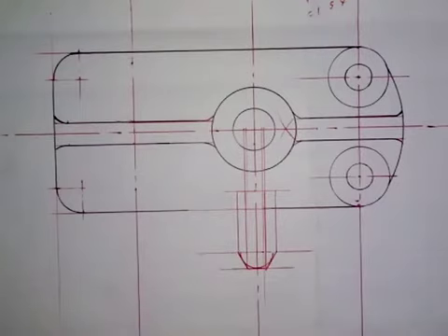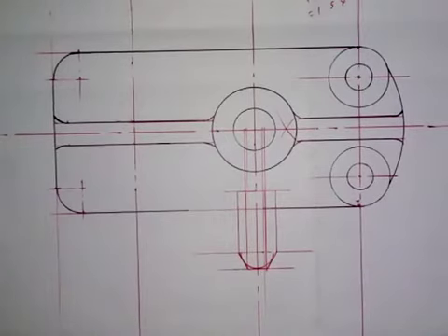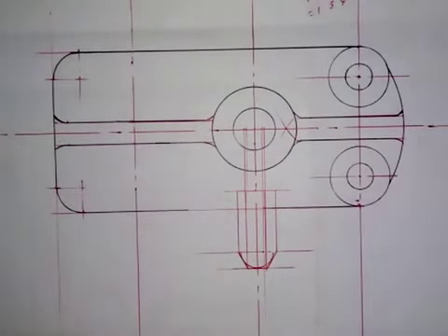the thickness of the hexagonal head is not given. The thickness is not given. So there is a formula that we need to make use of, but I don't want to use that formula. So that formula is 0.8 times D. So 0.8 times D, that is going to give us, so that's 64. So that will give us something like 6.4. So that's 6.4.